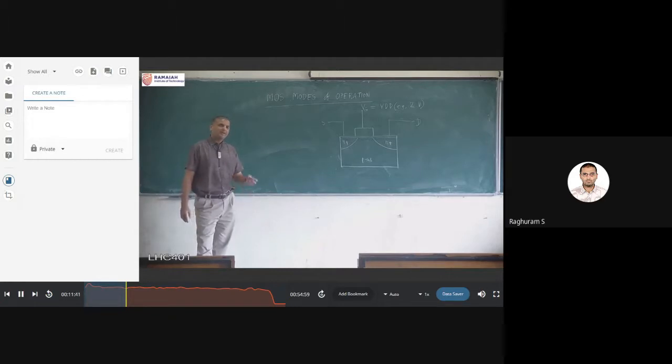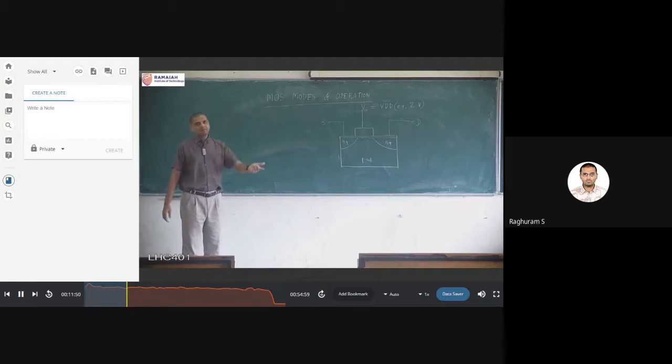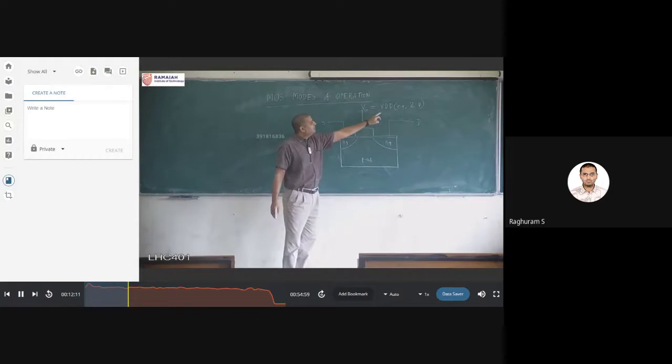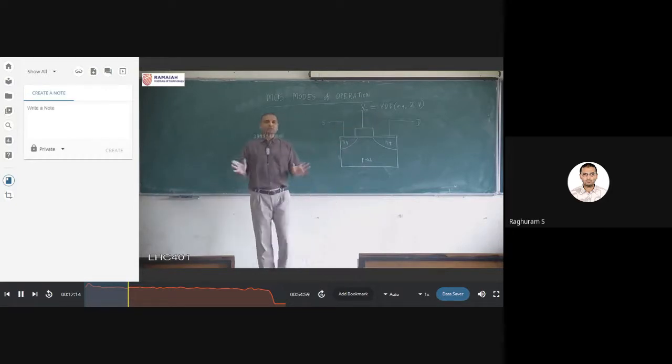So your laptop, for example, has a charger that is taking the 230 volts from our mains and converting that to around 5 volts, and that is what is supplied to the PCB. And the PCB will have one more transformer. Before it is given to the IC, it will generally be converted to a lower value also. That depends on the circuit. It might be 3 volts, it might be 3.3, it might be 2, I don't know. But let us assume that it is 2 volts for now. So that is what we are giving to the gate, voltage equal to VDD, 2 volts. So nothing bigger than this for our circuit.